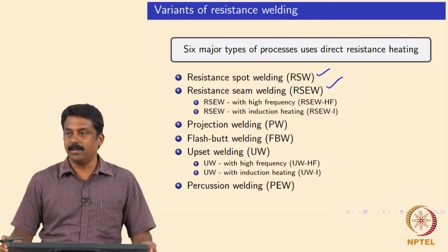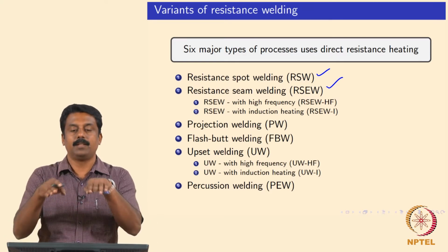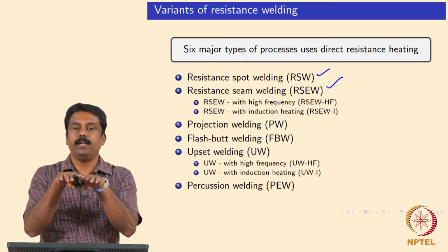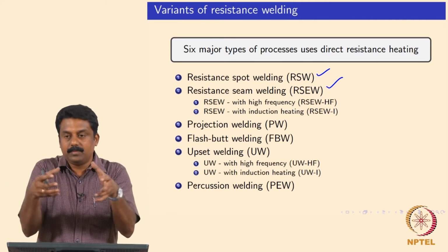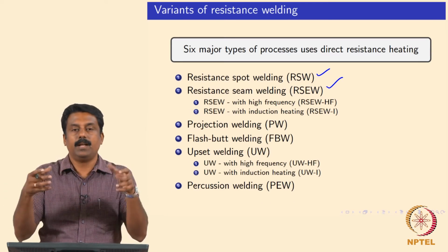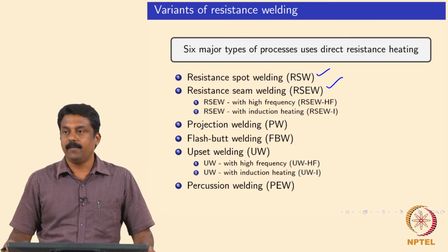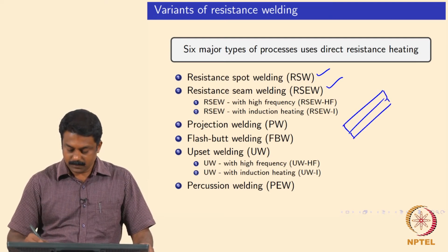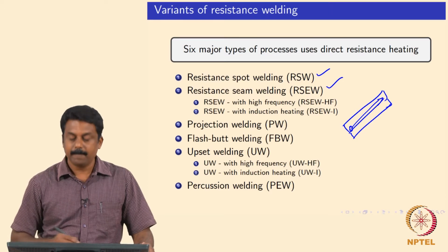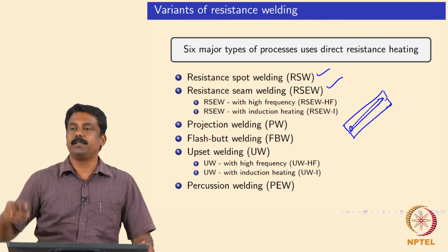In most applications, tube making is done by resistance seam welding, or ERW, electrical resistance welding, where the sheets are folded and we pass a current through the interface, heated by the contact resistance, and then do an upset to push it once it is heated up, and deform the edge to make a continuous seam. Or, instead of a spot electrode, you have 2 plates and an electrode rolled along the interface continuously, forming a continuous weld seam.